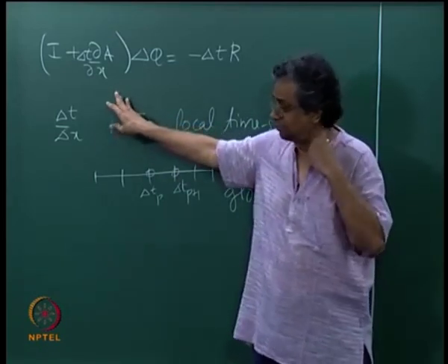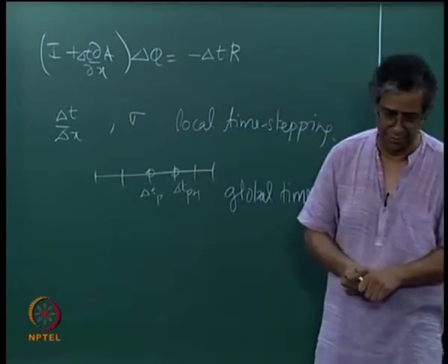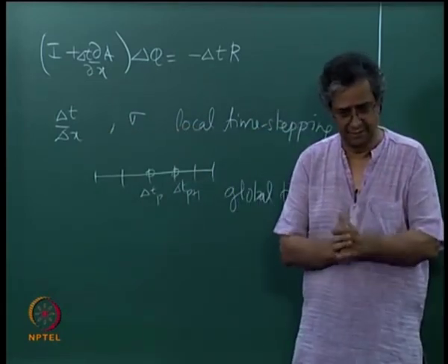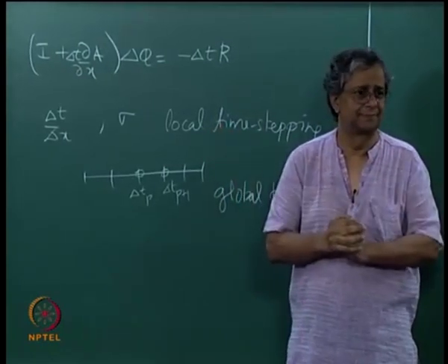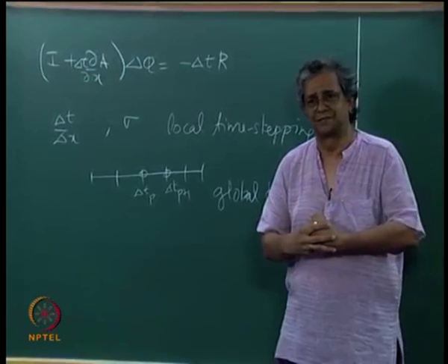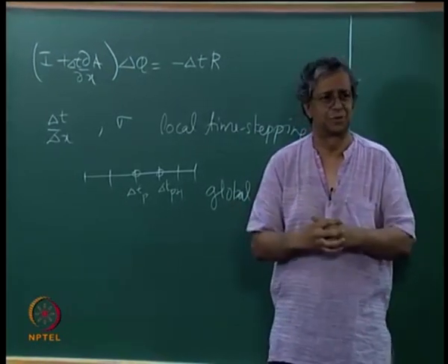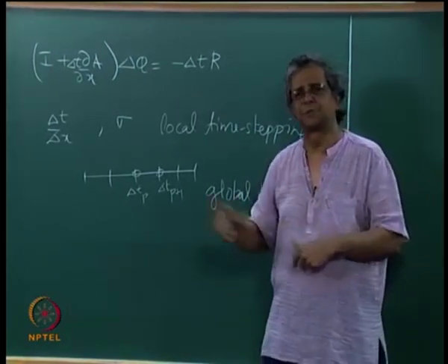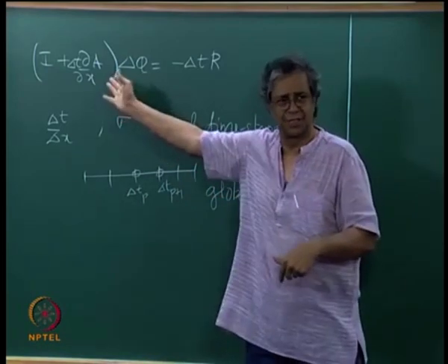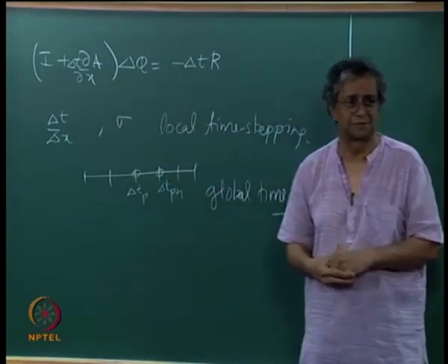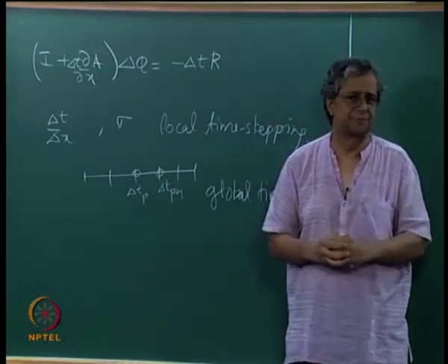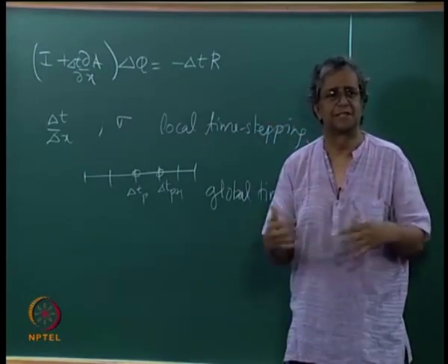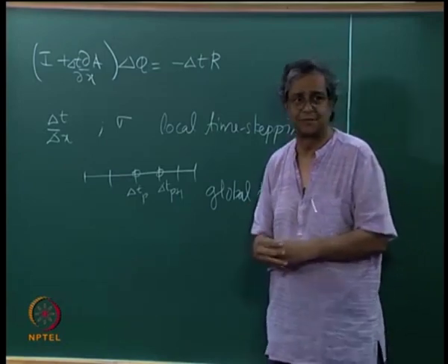We have typically found, well, it depends on the flow conditions, about 10 time steps. It depends on how rapid the transients are, but you are looking for the steady state solution. So in 3-dimensional flow, I am not really talking about 1-dimensional flow. You can try it out for 1-dimensional flow and see if it makes a difference. That you keep it constant for about 10 time steps, 15 time steps, that the savings are quite large. Okay, the savings are quite large.